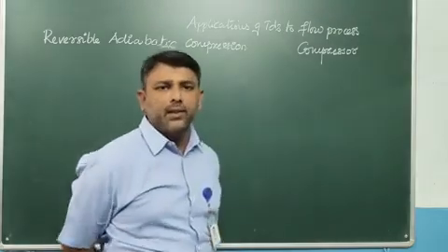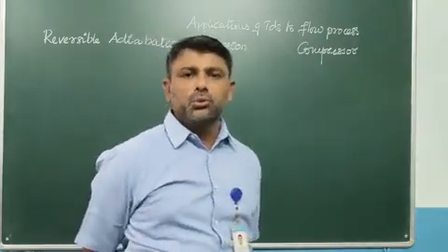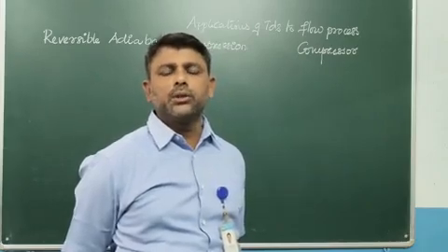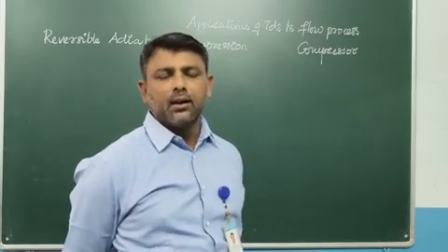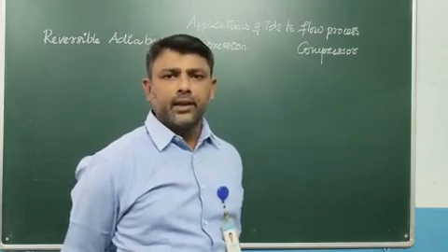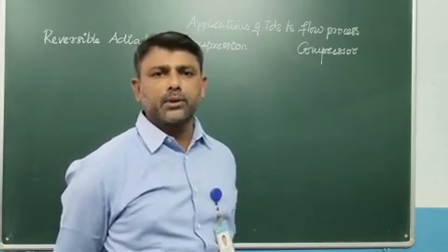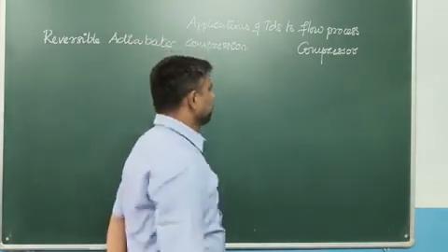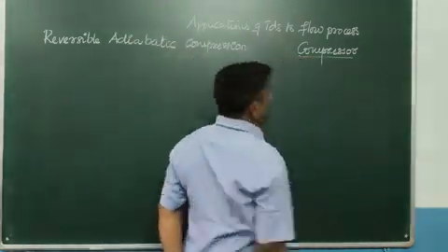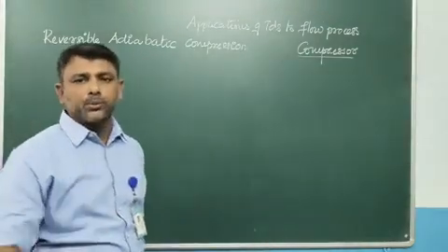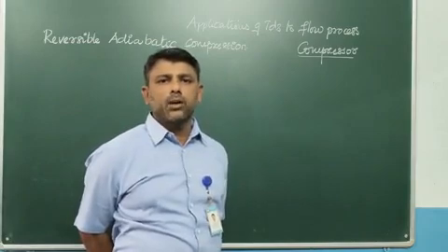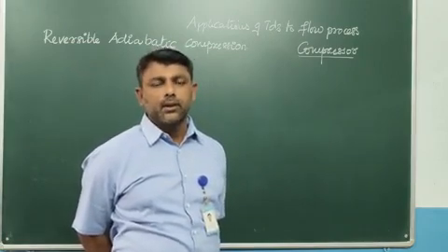A compressor is a device used to compress gas or air, or to increase the pressure of the working fluid, air or gas, from a given pressure to the desired final pressure. Clear? Compressors are of two types. One is the reciprocating compressor, another is the turbo type or centrifugal type compressor.